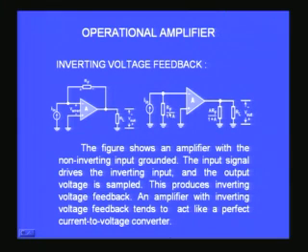So the resistance at the input will be divided by 1 plus A, because A is very large, RF by A will be very small. So this comes in parallel to the input resistance, therefore the effect is to reduce the input resistance enormously. At the output side, the Miller's resistance will be A times RF divided by 1 plus A. Because A is very large compared to 1, this is almost equal to 1, and therefore it will continue to remain as RF. The entire RF will approximately come in parallel at the output along with the load, and therefore the output resistance is reduced effectively because it is a parallel value.